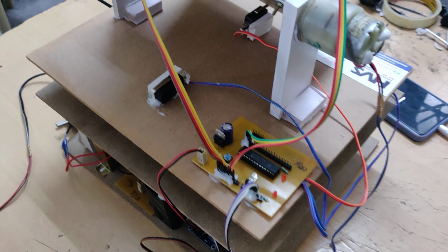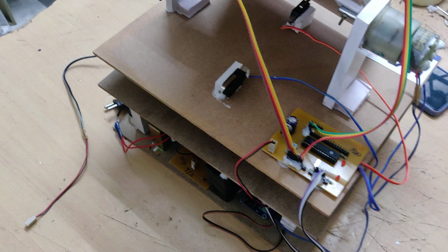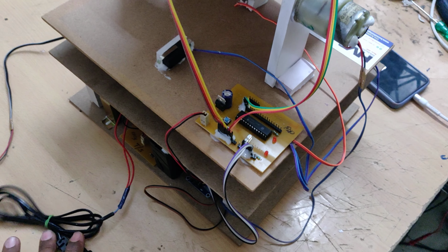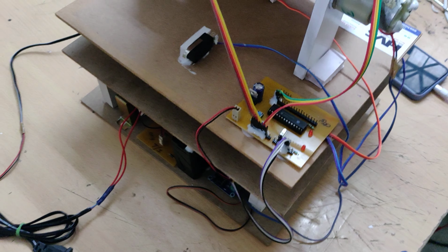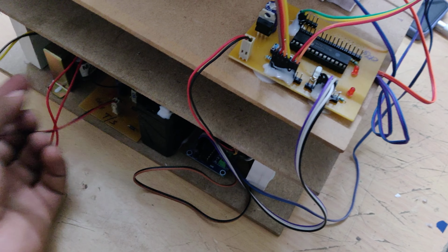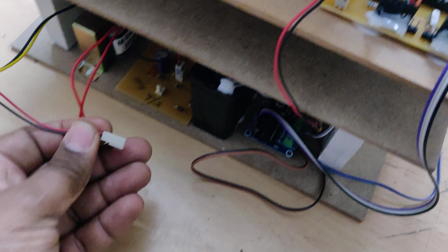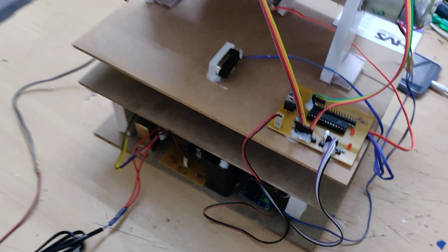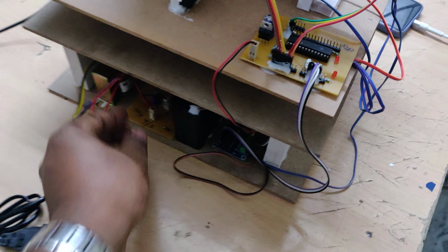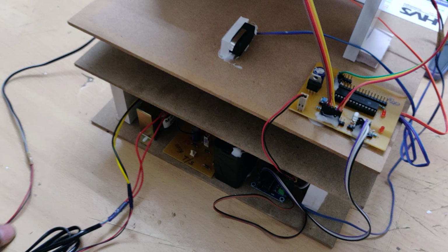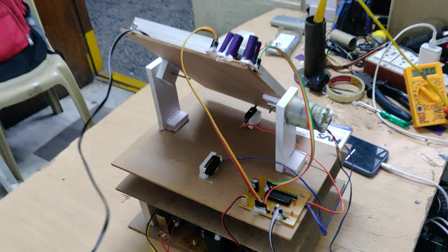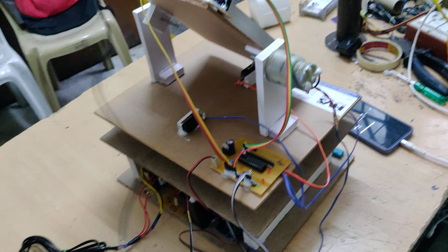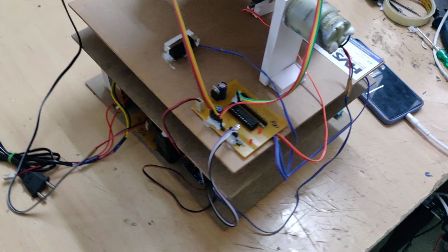So here we are providing two ways of charging. One is from the solar panel and another is from the transformer. If the sunlight is not available during the night time and you want to charge the battery, just connect this cable to the 230 volts AC input, and we need to connect the transformer. See it clearly, this is a transformer, T at this T or S slot. So when you want to charge a battery from the transformer. If you want to charge a battery with the solar panel, disconnect that and connect this solar panel output directly at this slot.